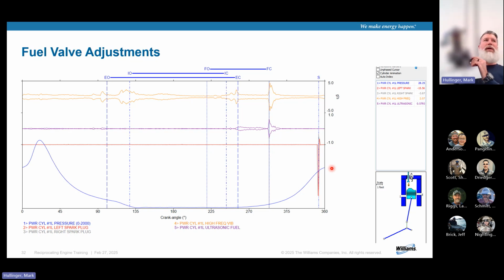Okay. So this right here, if I fire too early and I'm moving up right here and compression starts to push this thing down, or peak pressure, it starts pushing on this crankshaft when it's spinning one way. And this little moment arm, if it's too early, it's going to push down on the crankshaft and you got all sorts of damage happening. So you're essentially pedaling backwards when you're trying to go uphill, right? So that's why we sparked at that time.